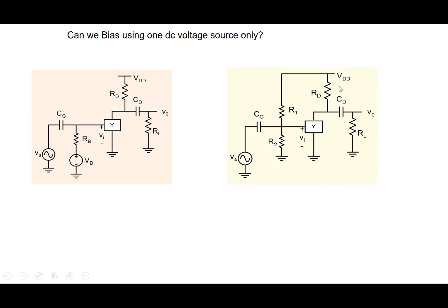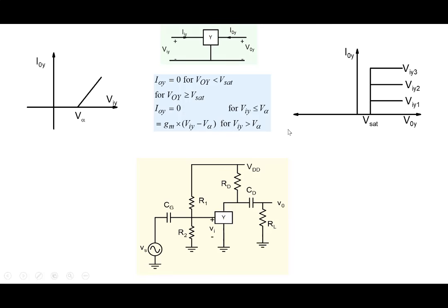And so VDD is chosen as larger than VB, and therefore the value of VB that was going here as DC voltage here comes through the R1 and R2 voltage divider. So it is easy to see that VB will be equal to VDD, R2 by R1 plus R2. So by suitably selecting this ratio R1 and R2, we could get the same effect as this VB and RB that you see. Okay. All right, so that becomes our revised schematic here.